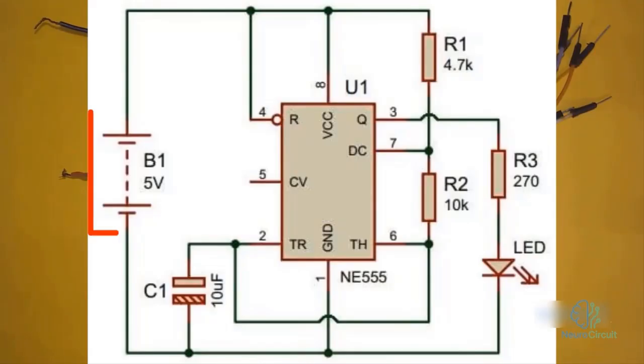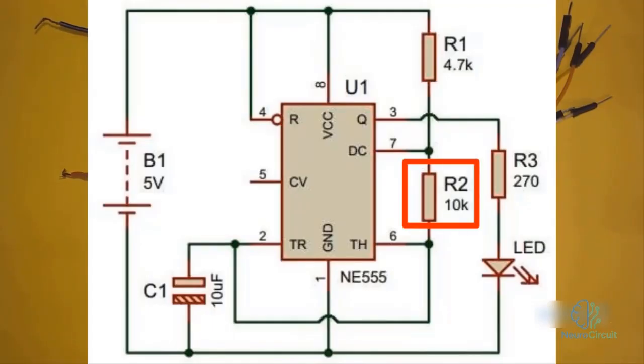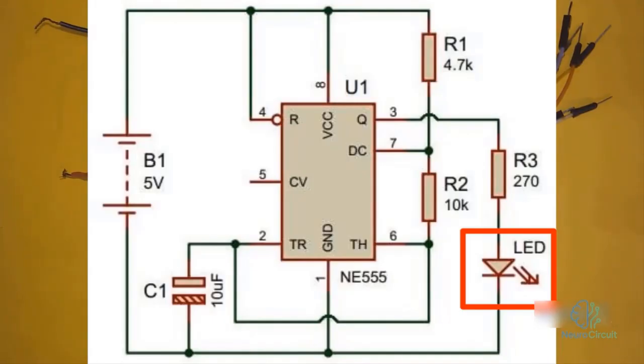We also need a battery and a power supply, and as we mentioned, the 555 IC works between 5 to 15 volts. Here, I brought a 9-volt battery, but if you're using a power supply, that's much better. But in the astable circuit, which you can also see here in the schematic, we need a 5-volt battery. We also need a 10 microfarad capacitor, a 10 kilo-ohm resistor, and an LED, and we're going to assemble it according to this. So you can get the components I mentioned according to this schematic.